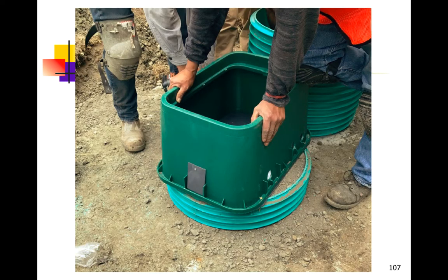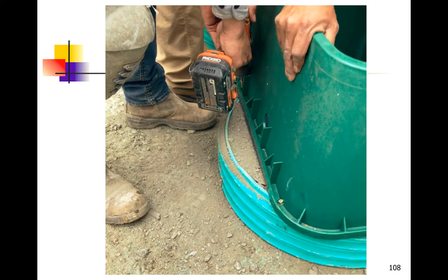Now, if you have a situation where the risers are going to be taller than 12 inches, what you'll want to do is cut a supplemental riser, the difference between the riser height and the valve box. In this case, our riser heights are 18 inches, so we cut a piece of riser pipe 6 inches tall. We've placed it on the tanks where we want to put the headworks, filled the riser with soil, packed it down, so now it is an anchor, and then we'll screw the headworks right to the riser. So now it won't move whatsoever. This makes it easy in backfilling so you don't have stuff moving around on you.